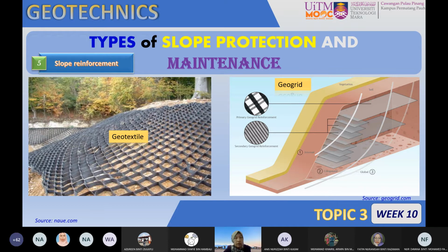The only difference between these two is the design of the reinforcement itself, such as the geogrid may be different in the size of the grid or the membranes of the geogrid. You can see the design may have different spacing and different length. The same goes for the geotextile. You can see the sizes for each space will not be similar. So there's a purpose why we use the geogrid and geotextile, but bear in mind also the cost involved. The cost involved in the project might be high due to this product.